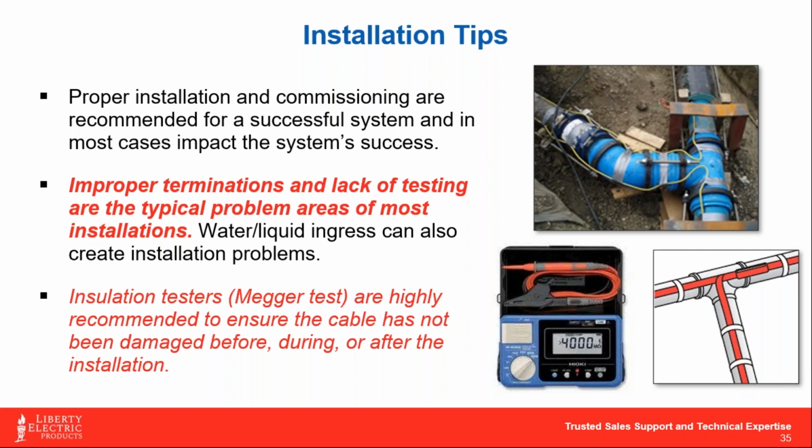So really when it comes down to it, as specifiers, I would strongly recommend that you either integrate startup and commissioning into the spec, an evaluation by either the manufacturer's rep, or the installers have to submit Megger readings, resistance readings, before, during, and after on the project, to ensure that the cables were installed correctly and that they're in proper working condition, to close out that portion of it.